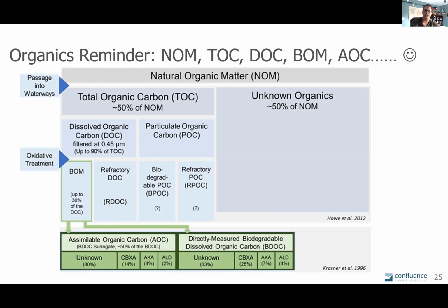And then underneath the DOC there, you'll see after oxidative treatment, some of that DOC can actually be moved into biodegradable organic matter, BOM. And how do we monitor that? That's kind of where the crux of the program here is, and what folks try to hone in on. Some of those monitoring characteristics can be very difficult and very costly.